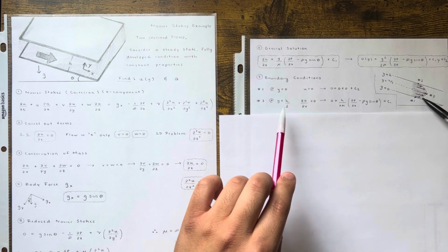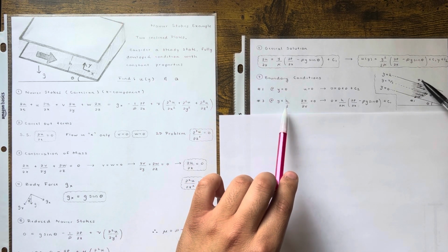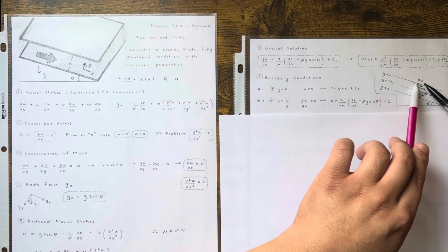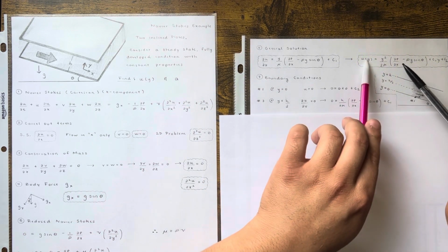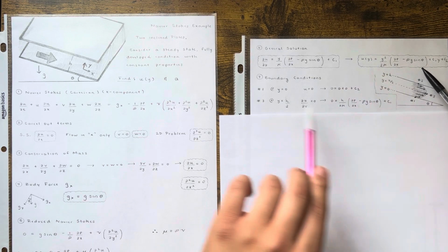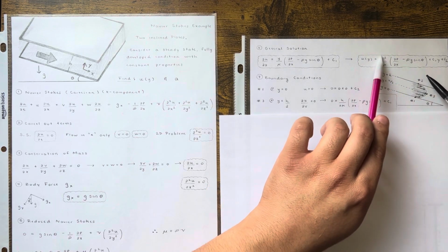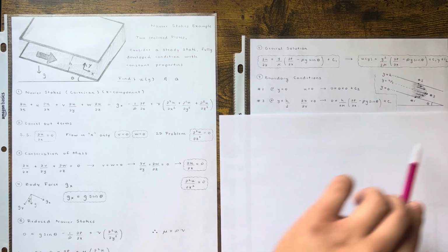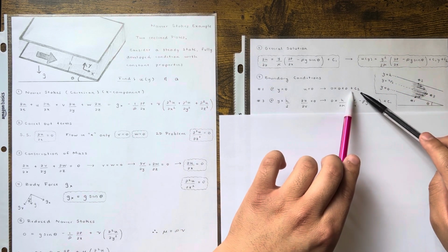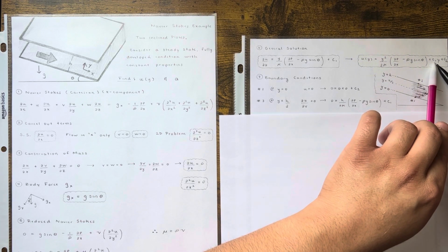Now, again, I could have done the other one. Let me go ahead and do it real quick. So at point number 2, velocity is 0, okay? So I would have used this equation: 0 is equal to, and for every y that I see, I'll plug in an h. So I'll get h squared over 2 mu times all this plus C1h plus C2. And then I already found out C2 was 0, so just solve for C1 in that case.